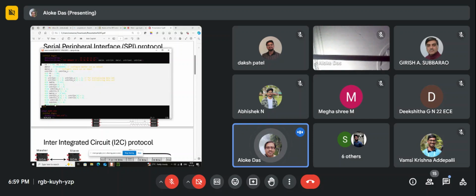See, this $finish will tell you. You have to add like this: from 0, this is 10, 10 plus 30 is 40, 45, 50, 50 plus 50 is 100, 120, 140, then 290, like that. And after this line, it will still simulate for 300 more time units, then it will stop.